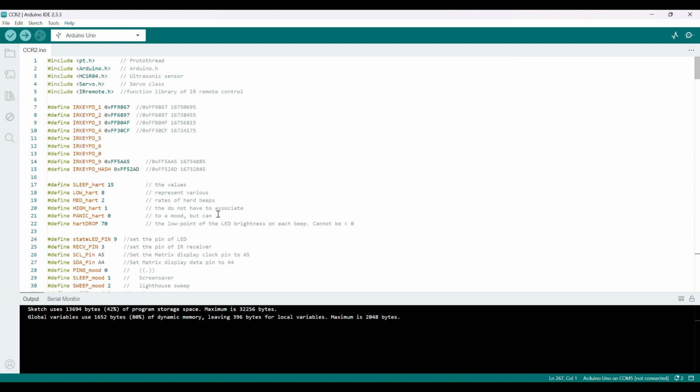At this point, we basically have autonomic things, the heart rate, the range sensor, the servo, all reacting to things, but we want to be able to suppress things. Specifically, we want to be able to suppress a movement. We haven't even got the wheels activated, but at some point we're going to activate the wheels, and we want to be able to suppress that movement. There are other things we want to suppress as well, essentially turning off a thread, overriding it temporarily based on the mood, the setting of the state.